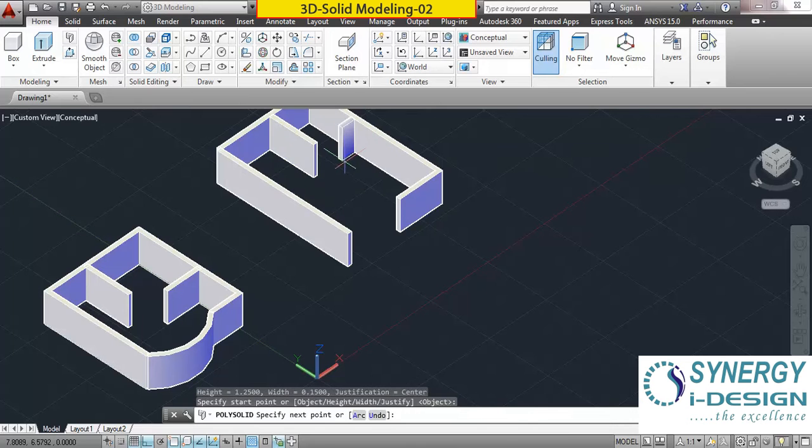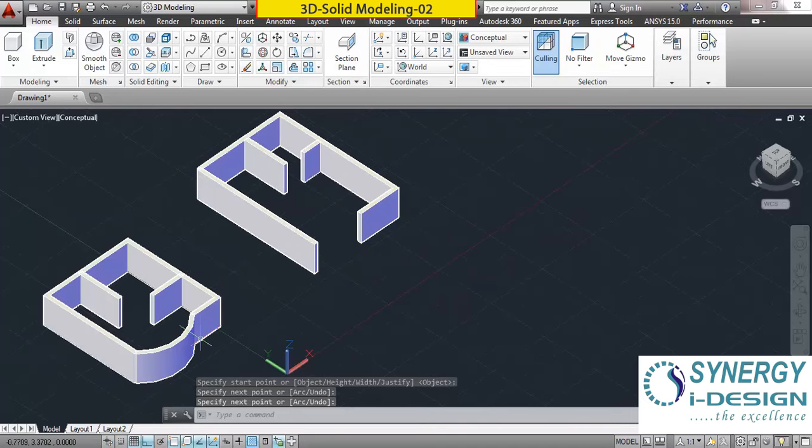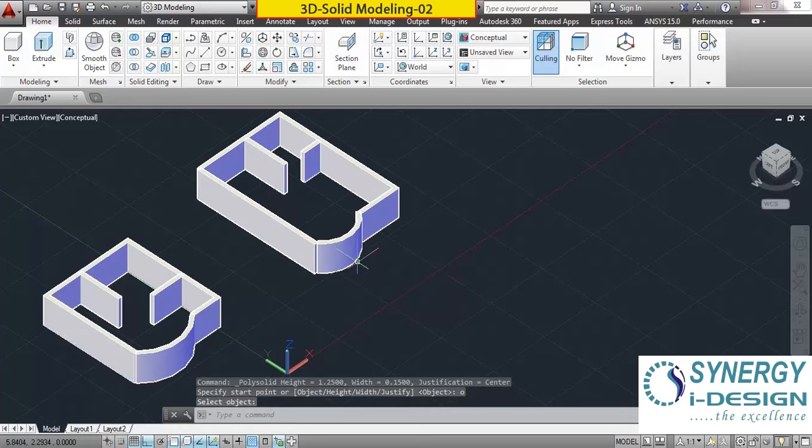Now I am clicking like this, because the location of this arc is not suitable according to this Polysolid. So for this, again I am creating an arc like this, and then I can create the radius of the arc, much greater than required. So I can create this directly from the Polysolid.